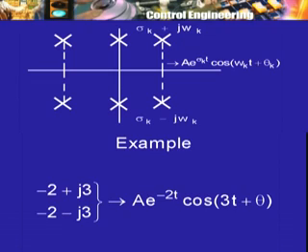So we have the following situation: if we have the poles of the transfer function such that none of them are also poles of the input transform, and the poles are all distinct, no factor is repeated, then poles which are complex and in the right half plane are bad, poles which are real and lying on the positive real axis are bad, poles on the imaginary axis are bad. A simple pole at the origin may not be bad, but may have to be examined because it may lead to steady state error.